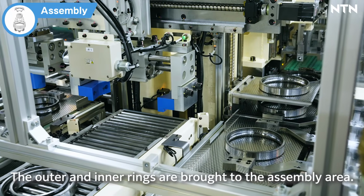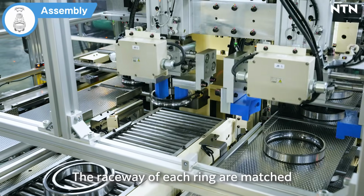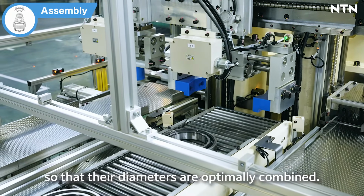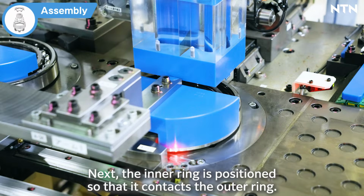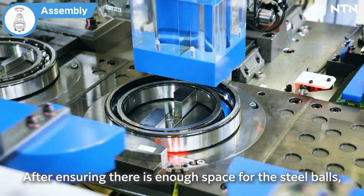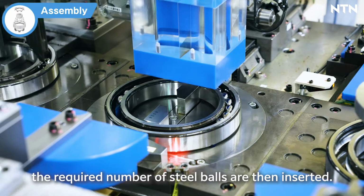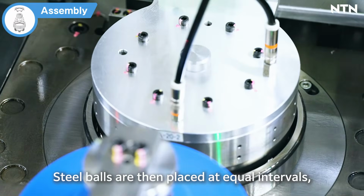The outer and inner rings are brought to the assembly area. The raceways of each ring are matched so that their diameters are optimally combined. Next, the inner ring is positioned so that it contacts the outer ring. After ensuring there is enough space for the steel balls, the required number of steel balls are then inserted. Steel balls are then placed at equal intervals.